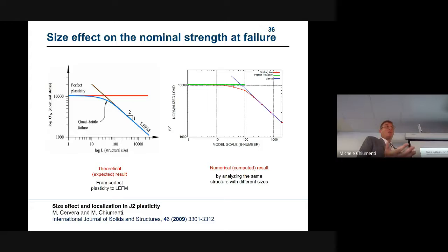We did exactly the same. We repeated it numerically, just using a tensile test you can find in the paper, just changing the size of the specimen, and you effectively get this kind of solution. These dots are the trials that we did. And you can see that without changing anything apart from the size of the specimen, you get a completely different solution, much more brittle than expected. This is called size effects. So particularly if you work in an industry building big structures, take care, because the failure is completely different from what is expected.